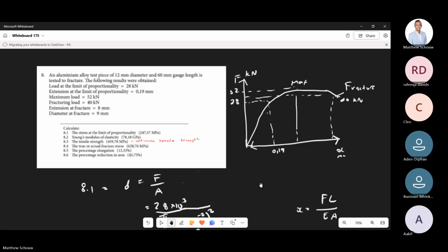Bring it. When it comes to getting the stress of this, you get 10 to the power 3 and then 10 to the power 6. Are you allowed to write it in gigapascals? Always write it in MPa. Would you? So keep stress in MPa. I can explain to you for days why, but you want to keep it MPa. And for E, you want to keep it GPa.